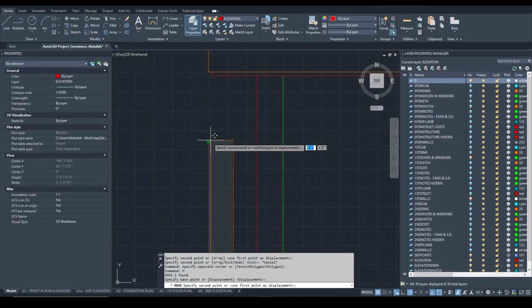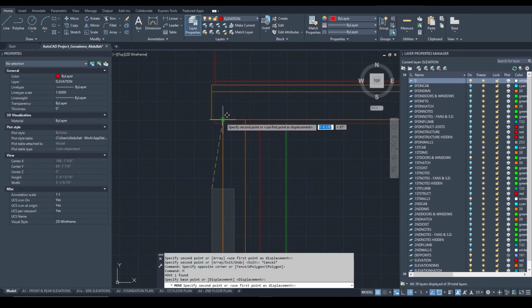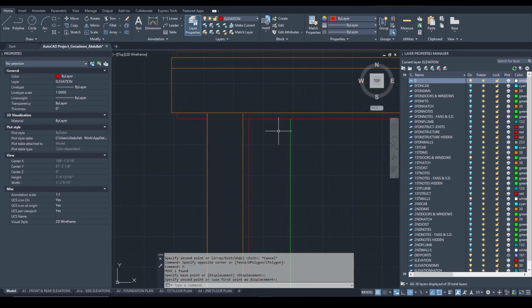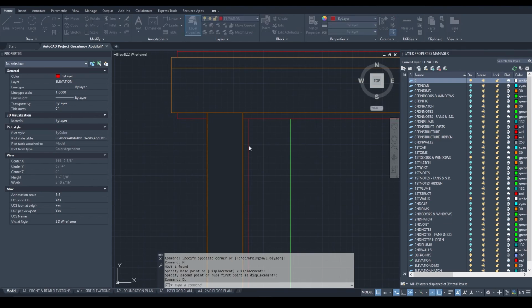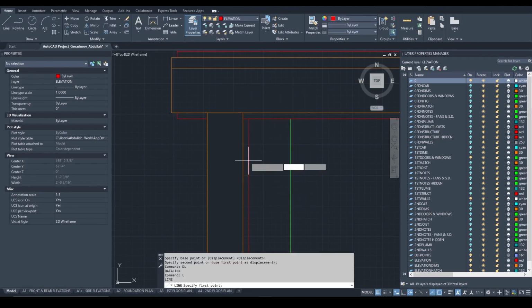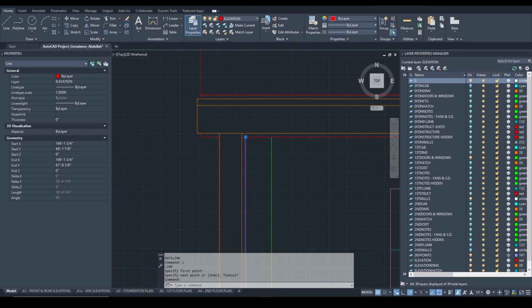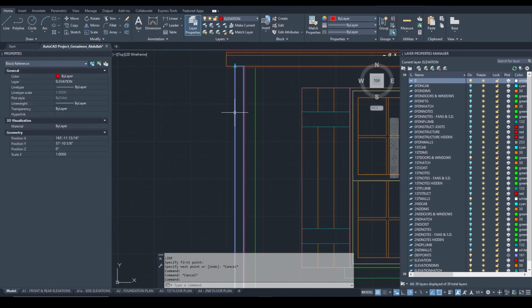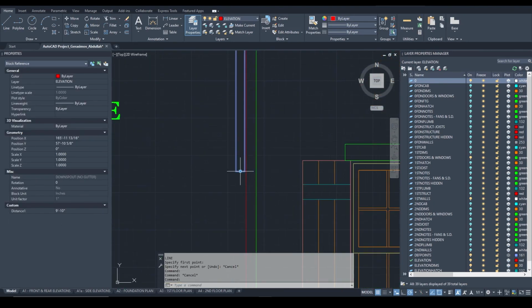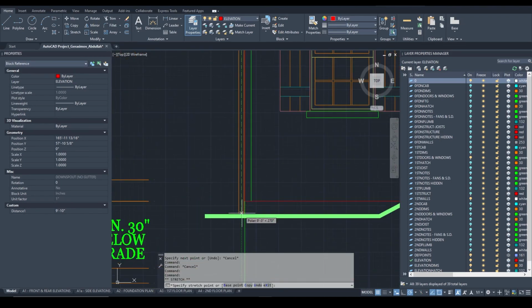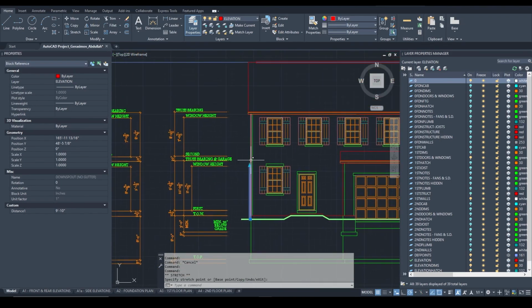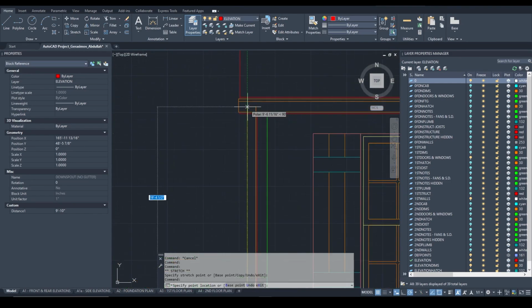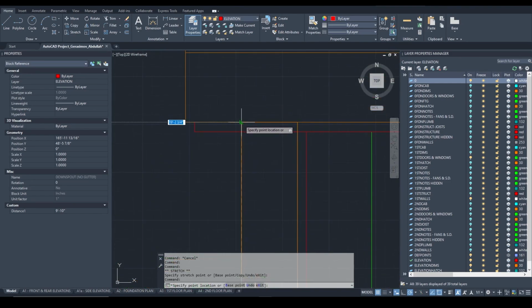Let's go ahead and put this right underneath the bottom orange line, but about half an inch away from the red line on the right side of our building. Half inch, I would say, would probably be the maximum that you want to put it against. Now that we have put it at the gutter level, let's go to the bottom of this rectangle, drag it to the grade level, which is the thick green line, and extend using the arrow above the same downspout to the same location.